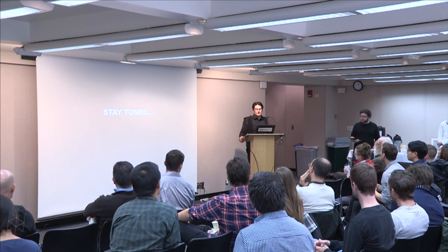Yeah, that's a great point. I think that Gehry is a kind of brute force example, right? I want this form, and I will force that glass into that form. And it's actually pretty innovative, the cold forming that Gehry did on the IAC building in New York. Basically, he discovered that glass is actually pretty flexible. Within a certain range, you could cold form it. And instead of having a million different unique panels, he had about 500,000, because half of these he could cold form into this geometry. I think he's still wrestling the material into the form, no doubt. But he's been pretty pioneering in testing the limits of what a material could do.